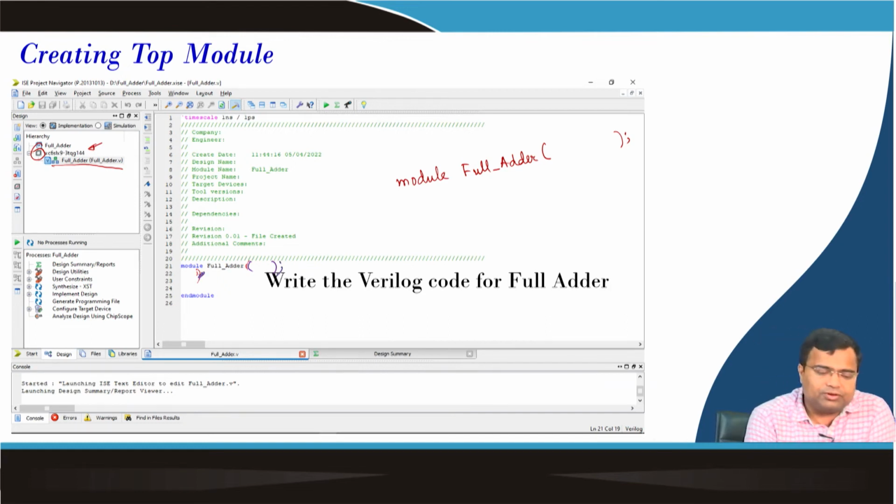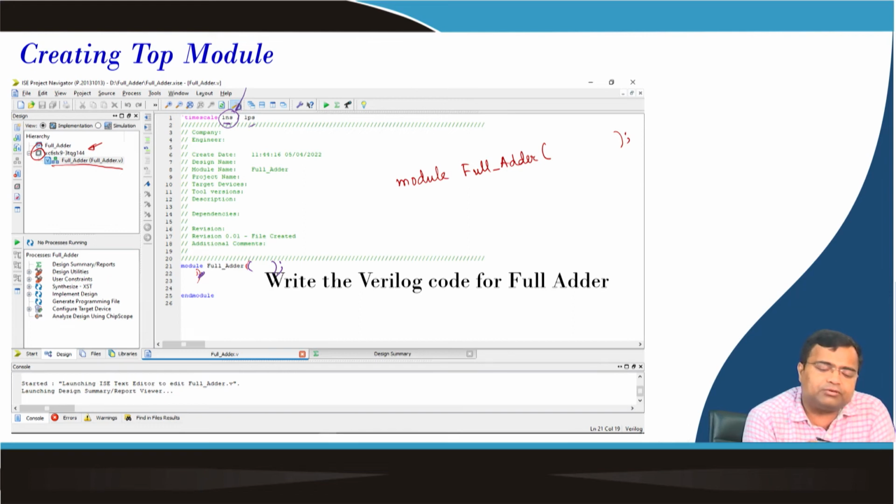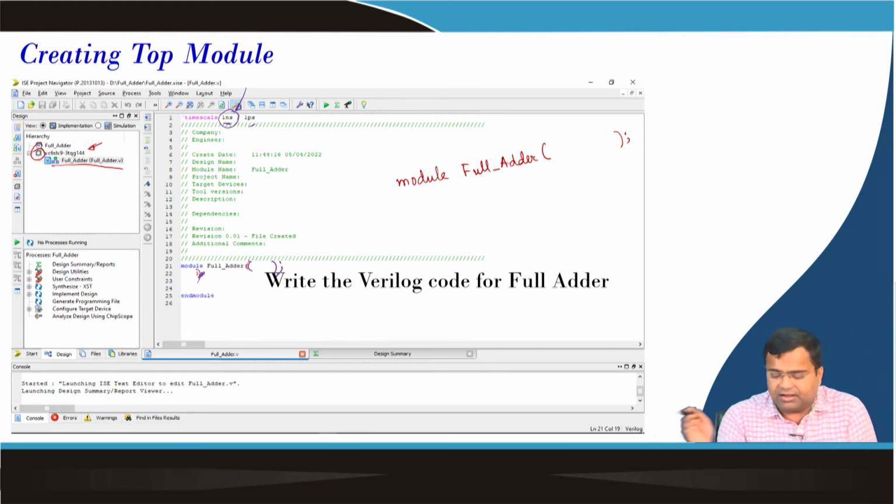So, you can take this here like this. Then end module. Now, here you will see the time scale 1 nanosecond, that is if you provide any time unit, 10 unit, 20 unit, it will be in terms of multiplied by 1 nanosecond. That means 20 unit corresponds to 20 nanosecond. And this 1 picosecond, suppose if you simulate more precisely, the decimal can go up to 1 picosecond. So, this value is more important. Okay.